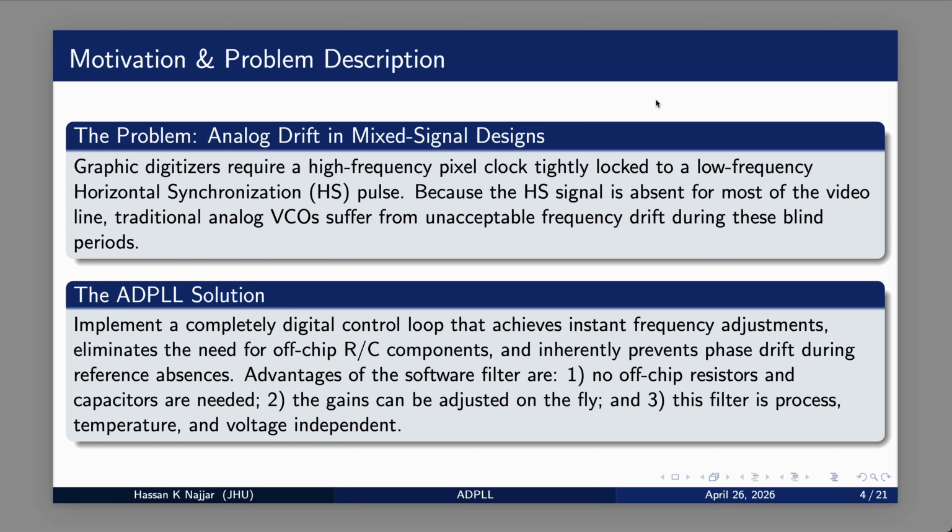The paper's solution is a digital loop built around a flying adder digital control oscillator and a software-implemented adaptive filter, giving fast digital frequency updates and eliminating the need for off-chip passive RC loop filter components.